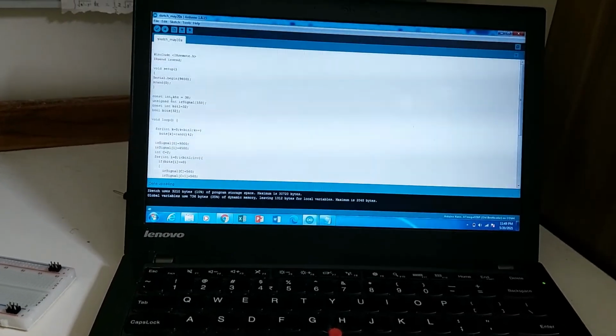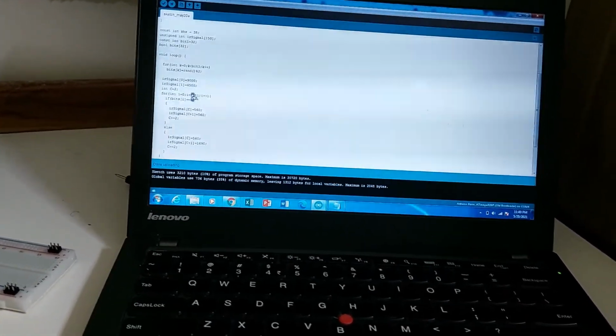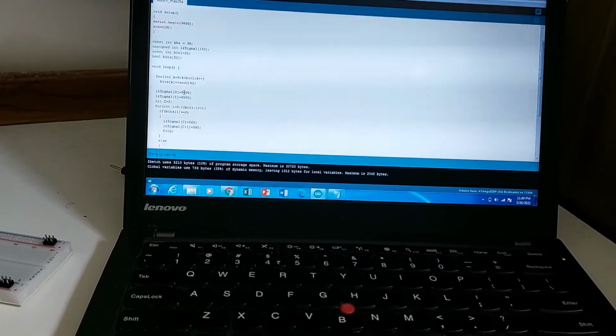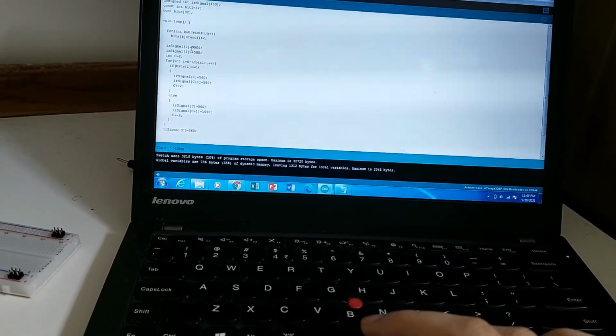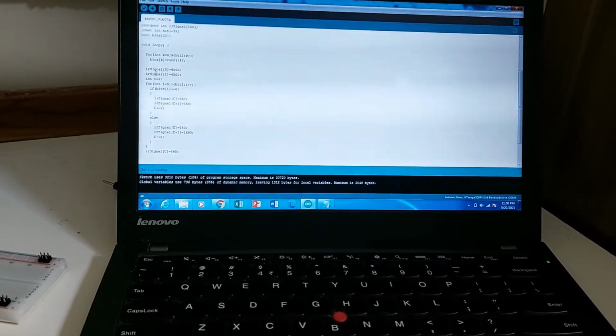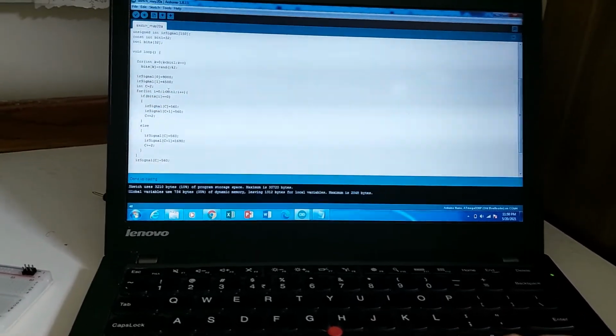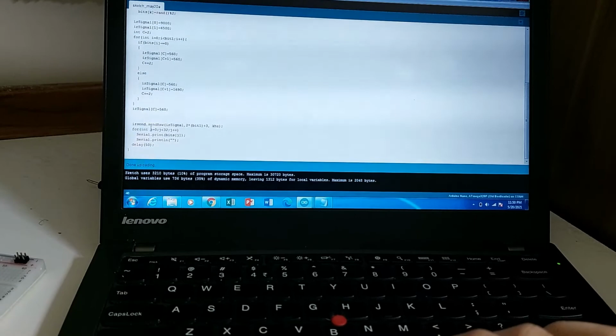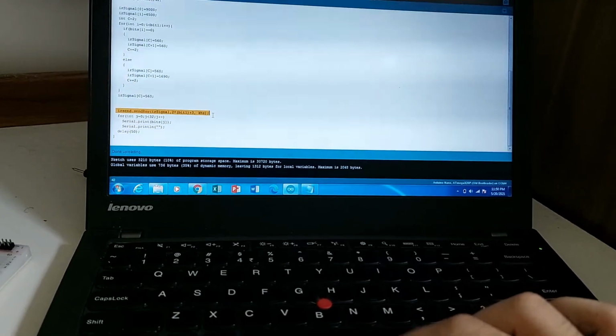Good morning, sir. The aim of this project is to send data between two computers using infrared waves. We have done that in a total of two ways. Firstly, using the NEC protocol, which is commonly used in TV remotes and other electronics. Over here, on this computer, we are generating 32 random bits, and according to those bits we are deciding how long each pulse and each space will be according to the NEC protocol, and we are sending it to the other computer.